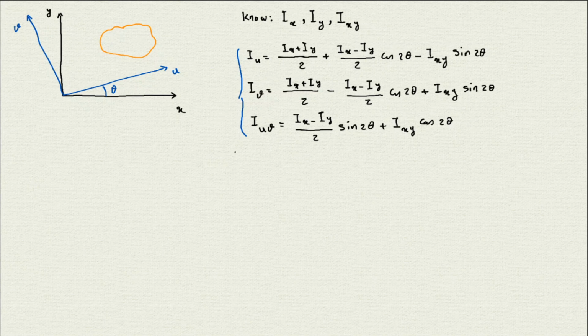One point about this is that assume we start from 0. Assume we consider theta as 0, and we start to rotate it, and for every value of theta we calculate this moment of inertia. Eventually, if we calculate the moment of inertia for all theta, we would find two specific values.